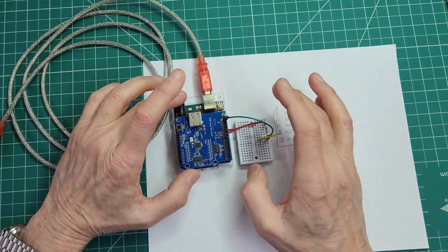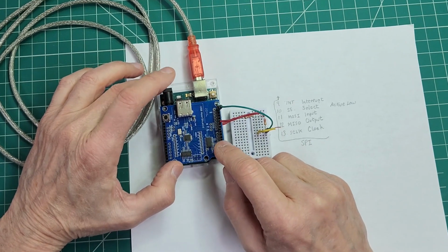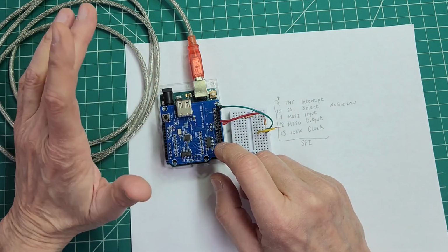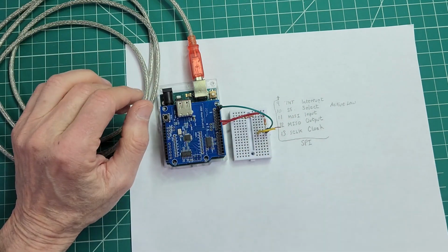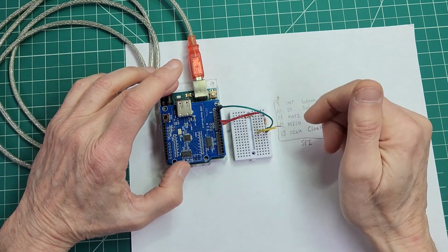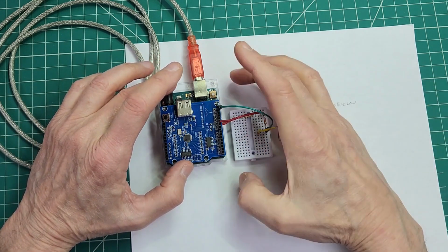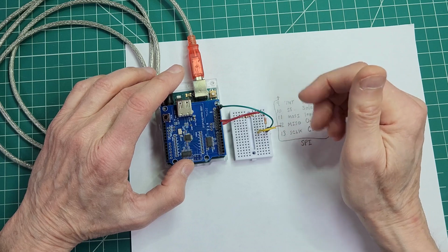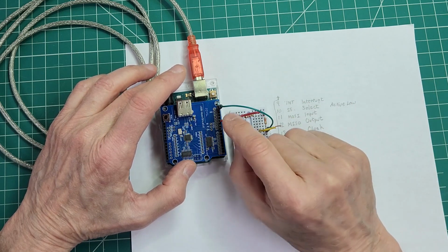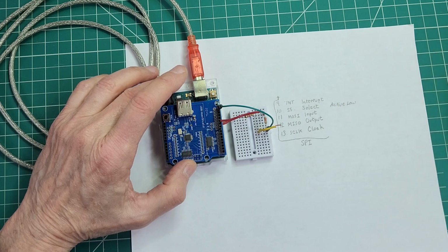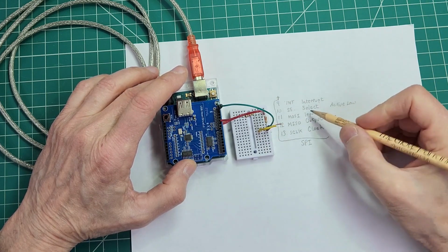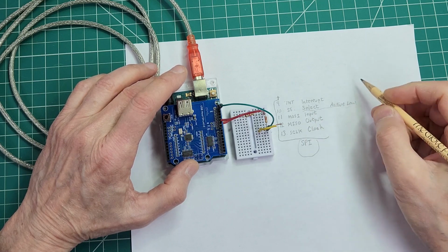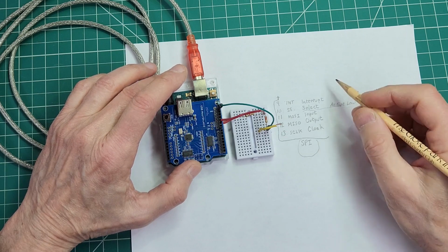One of the major causes for my frustration was the fact that I was never able to predict when I was going to plug in a device and have it simply not be recognized. So in this kind of configuration, I've been successful. And what's happening is that I've used the voltage divider that I had discussed previously and reduced the 5-volt output from the select. Now this select part of the SPI interface is active low. So it's typically high most of the time.